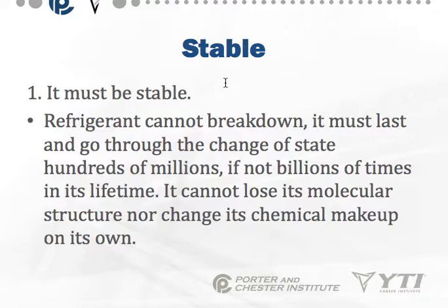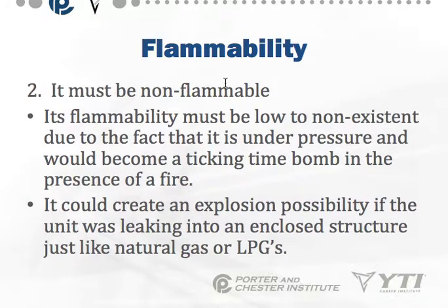You hear customers on occasion tell you that a prior technician or a prior company said they have to change out the refrigerant on a system. This is not accurate. You should never have to change the refrigerant on a system unless there's a breakdown of the compressor oil and the compressor windings, okay, which will cause acid. Then you have to recover and recharge and clean the system out.